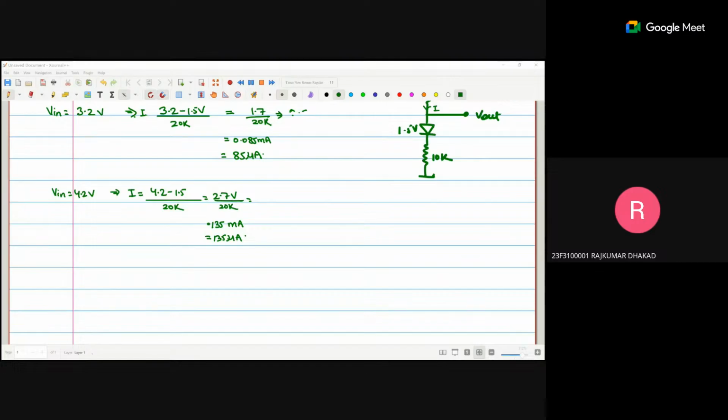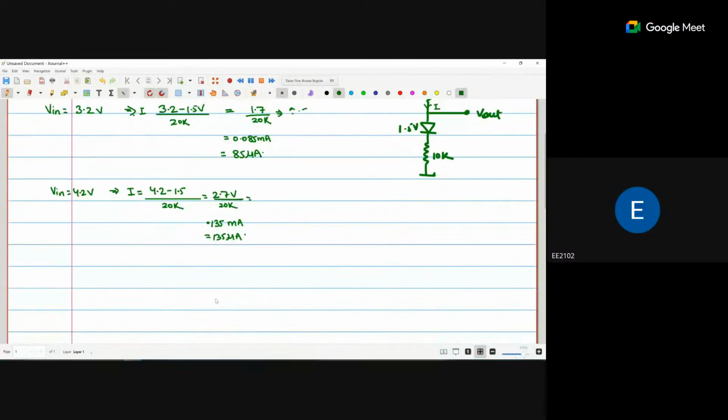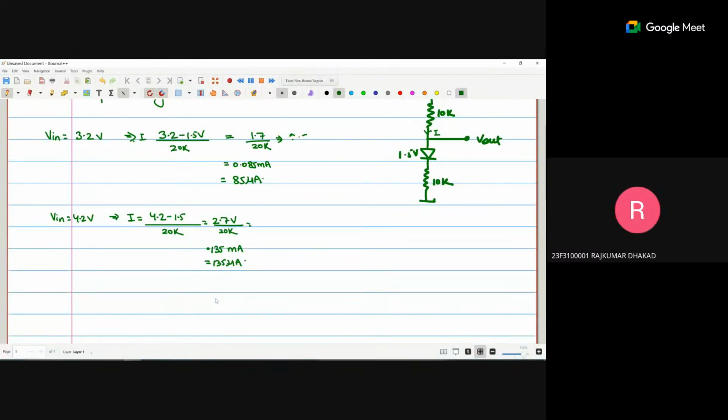By definition, it is I think millivolt per volt. Yeah, millivolt per volt. Then why is it asked in the question in terms of milliampere? I think there's a problem in that one. So for that the load current should be given to measure the load regulation. IL is basically